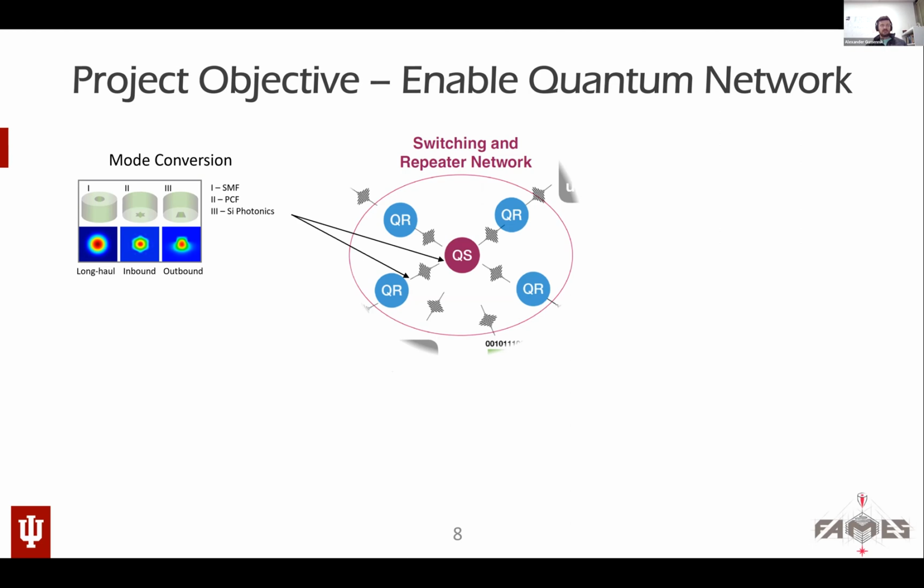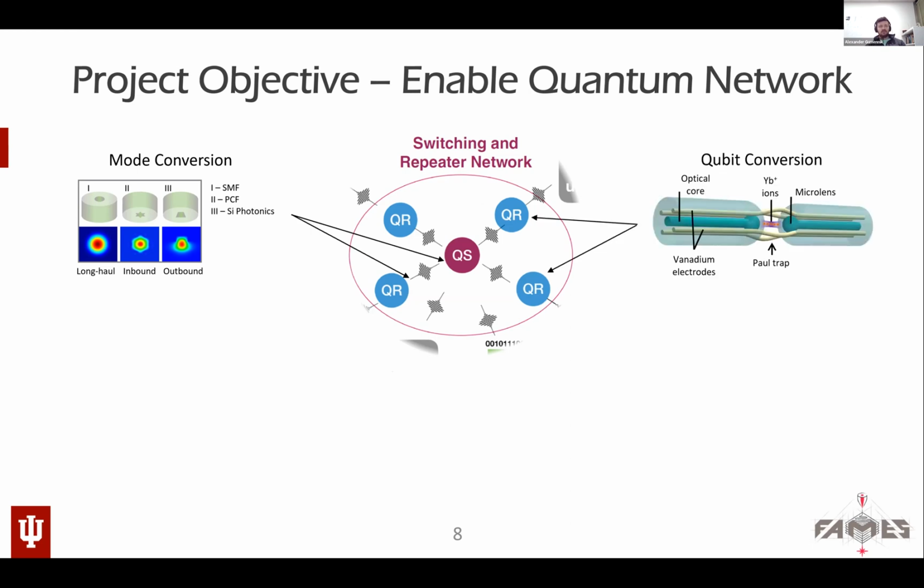So basically, you need to have some kind of a fiber, which on one side looks like a 6-fold, on the other side looks like a circle, in order to couple the mode from the atomic trap to the long haul fiber communication cable, and then back from the long haul communication cable into the silicon chip by an adiabatically changing taper that translates circular mode into trapezoidal mode. That's not something that current fibers are designed to do.